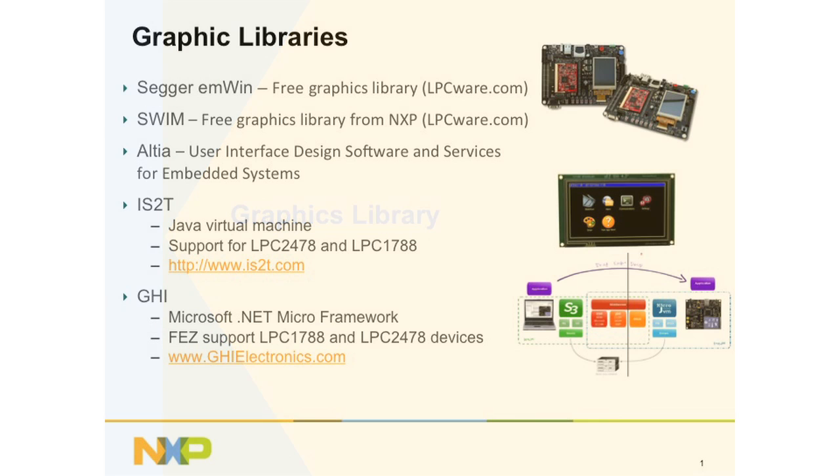Now, you've got the LCD, so what's the best way to actually, from a development platform basis, we said we need to pick a certain graphics library to really showcase the key features of it. NXP is partnered with Segger. They have a graphics library called emWin. If you buy an NXP microcontroller, with or without the graphic LCD, you can get emWin libraries for free. That doesn't include source code, but it has everything you need for the GUI to go and build your own graphical interface. So very nice package.